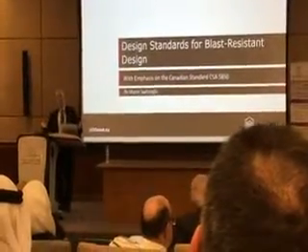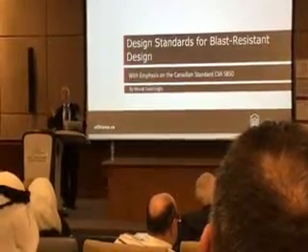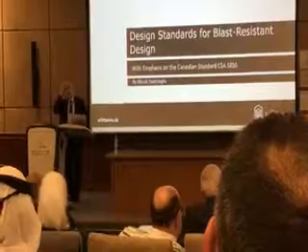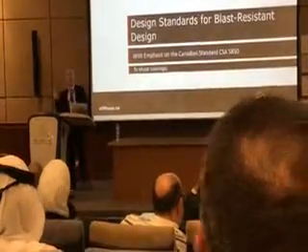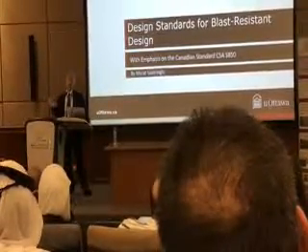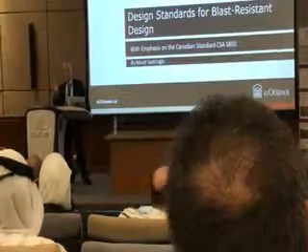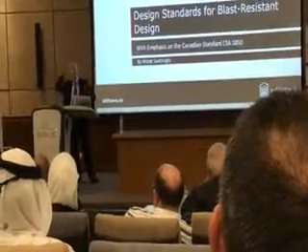But if front and sides have the same strength, then it is sufficient to do only the front load analysis, because there you have very high pressure, right? But if you're designing beams that may be supporting your roof, then of course you need to know the roof pressure. So typically you do front, side, and roof.